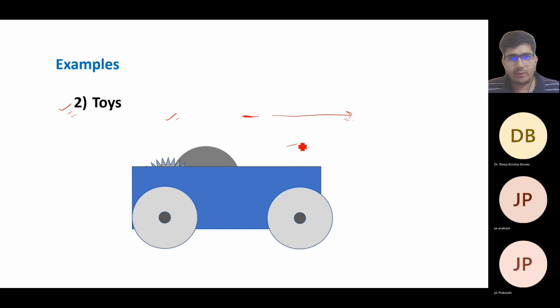So when you are pushing or rubbing the toy against the surface and not releasing it, in that time the rear wheels are rotating and they are connected with the flywheel. This rotation of the rear wheels gives energy to the flywheel, and the flywheel stores that energy. So when you release the toy, that stored energy comes back to the rear wheels and the toy moves forward.